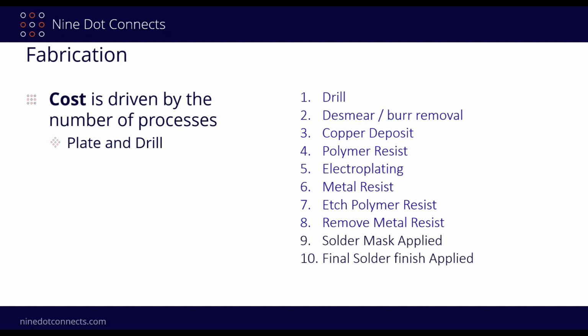And I wanted to just bring this to your attention because every time we add in another type of via other than the through hole, we expect a through hole, right? Otherwise, we won't have multi-layer boards. But if we add in other types of vias here, every time they have to stop that process and they got to drill and plate, this is exactly what they're going to go through.